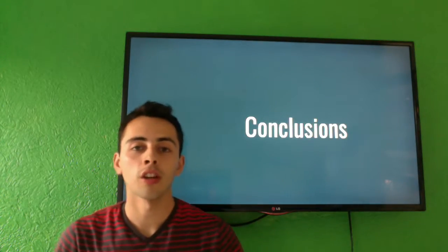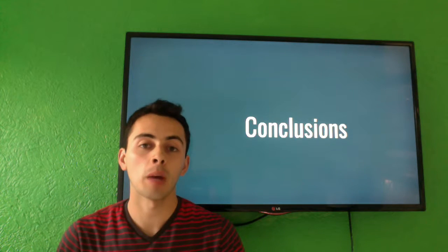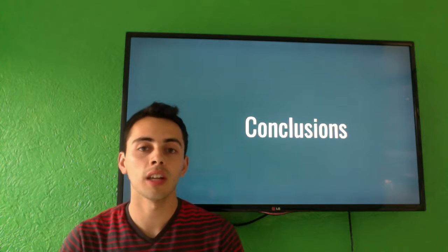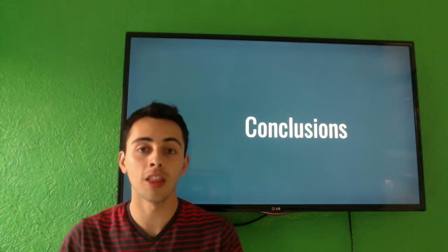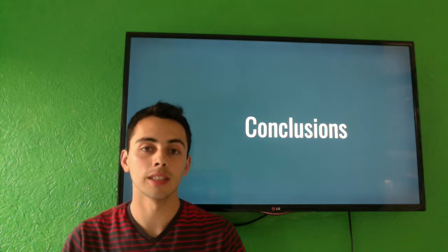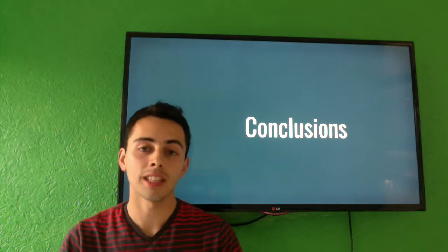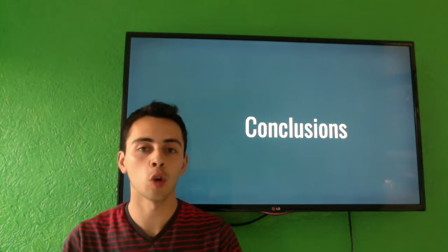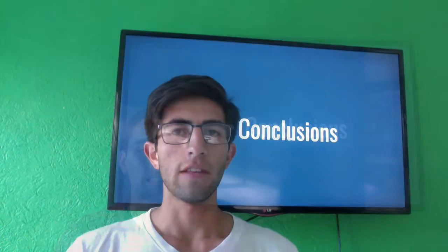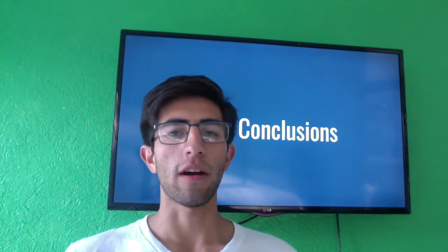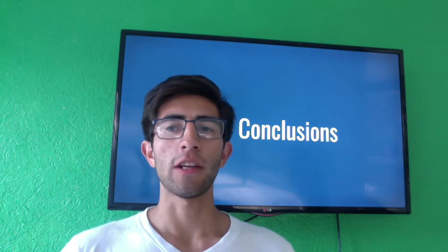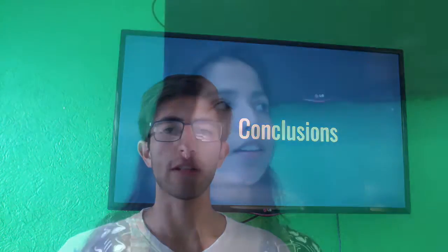In conclusion, I learned that welding can affect the properties of a material, and this should be known because otherwise the material can have a weakness inside it in the weld, which could damage the material in its application. In these cases, other treatments like normalizing or annealing should be done to recover the original properties. And in this practice, I learned how arc welding affected a steel plate through all the different zones, like the fusion and heat affected zone.